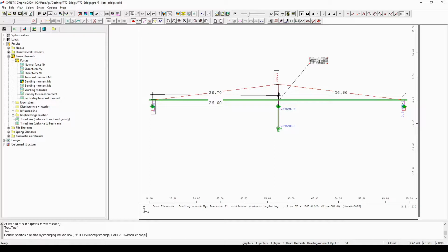the text if I want to, for example, make it a little bit smaller. Now I need to hit the enter button once more and then click on the escape to terminate the command. And as you can see, this is how I can insert a multi-line text if I want to. In a very similar fashion, the insert text with frame command will work for you, and also the insert position symbol or insert level symbol.